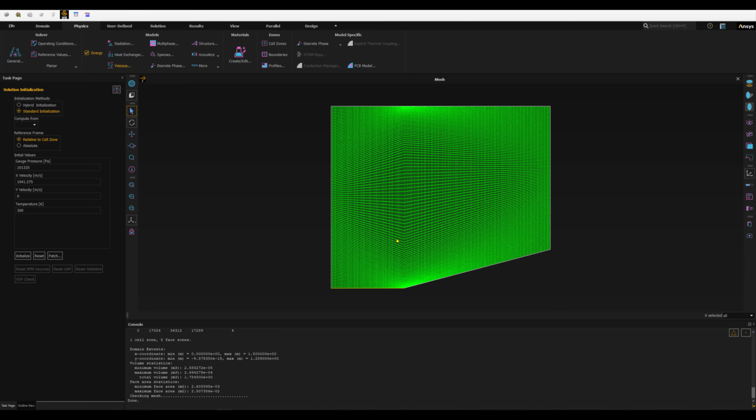You will see we are using a relatively dense mesh for this setup. You can use a coarser mesh, for example, by setting the element size in the meshing part. You can select an element size of 0.04, for example. Then you have better convergence, I mean, you will reach convergence very soon. But then you need to adapt the mesh, because you will have a shock here, so you need to modify your mesh with mesh adaption. So that's another way.